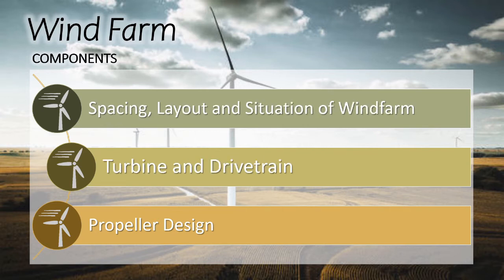In terms of the turbine and drivetrain, they play a crucial part of the design. They house the generator and the gearbox. For our design, we will be using a single-stage gearbox over a three-stage gearbox. This is due to a single-stage gearbox having less maintenance issues.